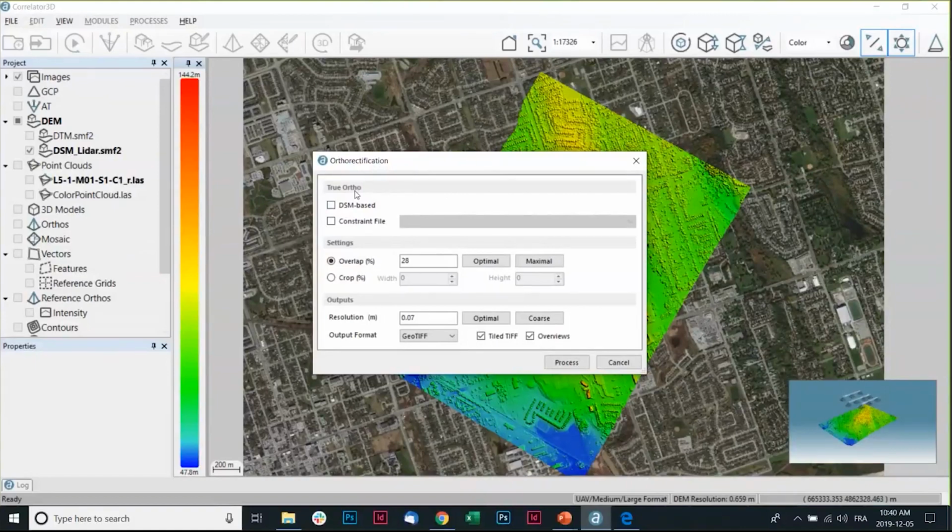Sometimes this could be interesting if you're flying a UAV at a really low altitude, where the leaning effect of buildings or elements is not rectified with a DTM ortho rectification. It could be good to crop the ortho a bit to reduce this leaning effect, so you should have a better result when you're generating your mosaic. Also, the crop factor should be in accordance with the overlap of your imagery.